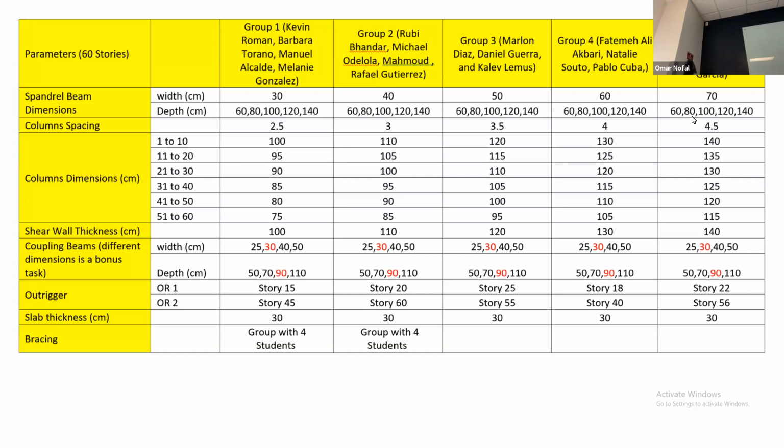So right now we build a base model. So let's see how we can do the parametric study. Once we build a base model, you are gonna, for example, try the next parametric study. So you are gonna save your model as and build another model. We are gonna do a few changes to the base model. You are gonna select all the beams that have dimension 30 by 100, and they are called spandrel beams, and assign a new beam that has dimensions 30 by 60.